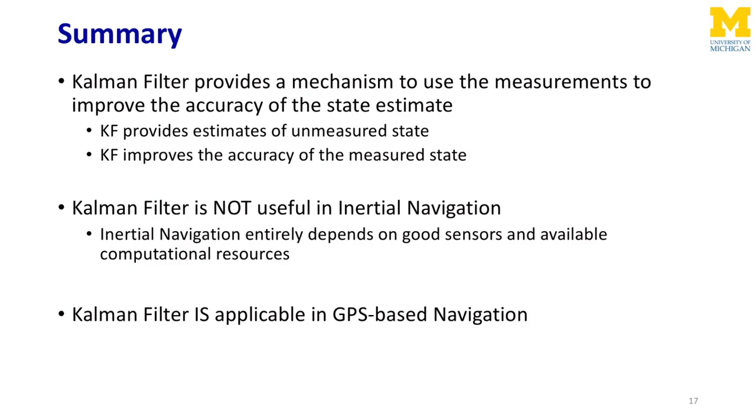But for applications where GPS or any other position measurement is available, we can apply Kalman filter. And of course, since Kalman filter is fusing the measurements with the same model that inertial navigation uses, its estimates are definitely going to be better than just the inertial navigation.